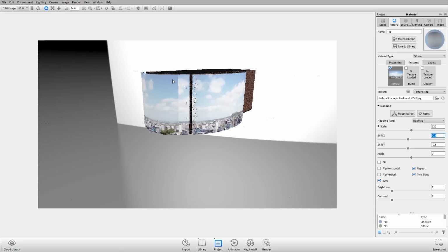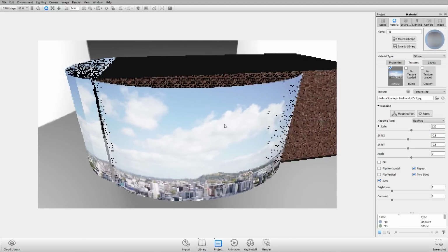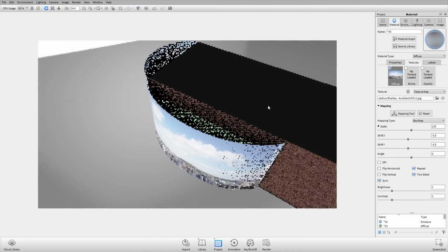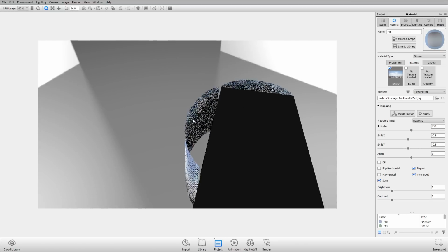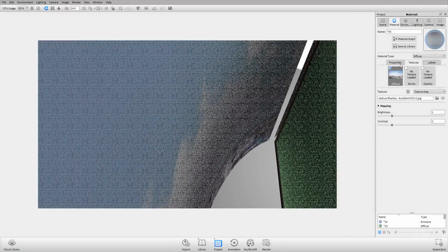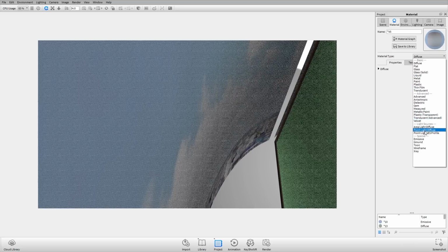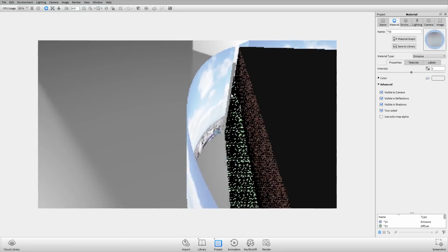But now we've got a view outside of our window, and we're not going to rely on our environment because that can be really tough. It's a lot easier to just put a piece of geometry out there, slap an image on it, and then have it set as our view outside the window. So same trick here that we did, or it's not really a trick, but I can change that material from diffuse to emissive under special. Again, it's not under light sources. It shouldn't be used as a light source. It's used as a special material. So I can set that to emissive.